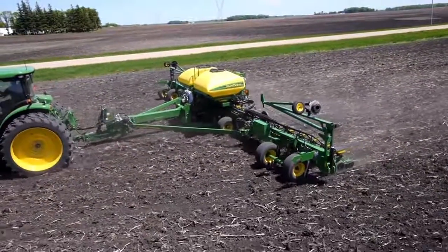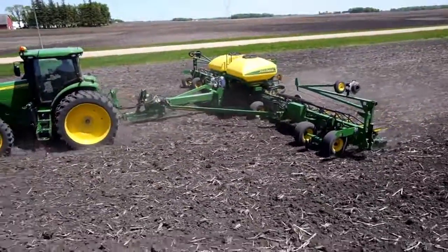Did you know that how you set up the tractor hydraulics can make a big difference in tractor efficiency? This video will explain how to use available resources to calculate and adjust SCV flow rates to supply only the required flow to each function. We will also show you how to use eco-on and eco-off engine speeds in custom mode to satisfy all hydraulic demands while maintaining the lowest possible engine speed.